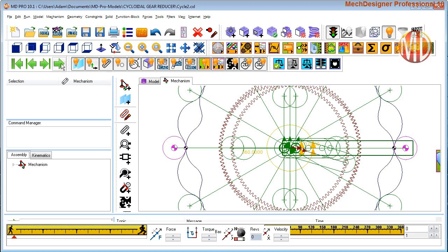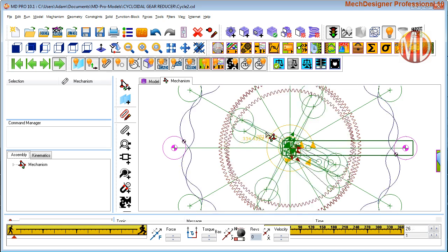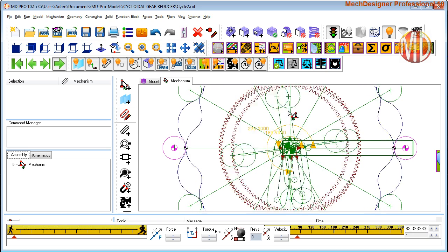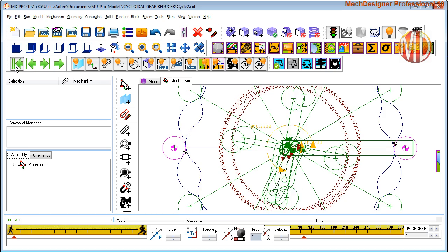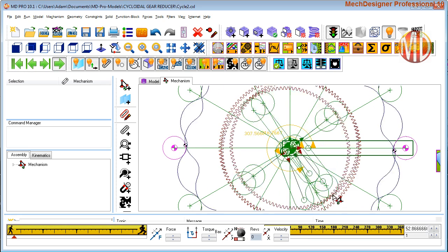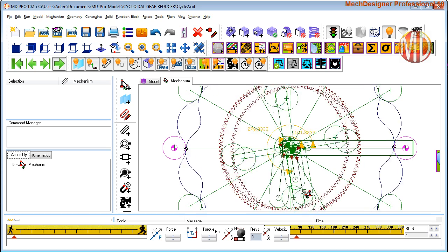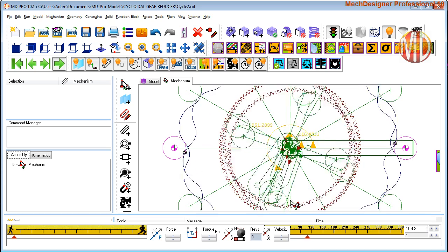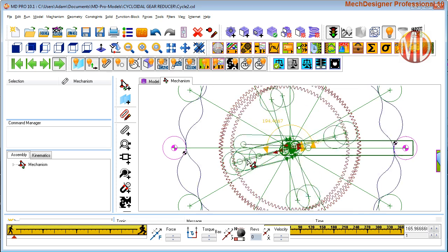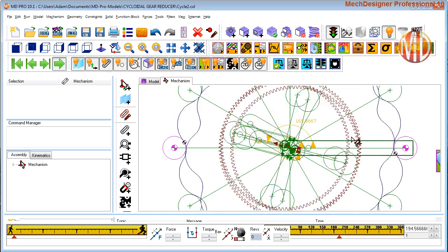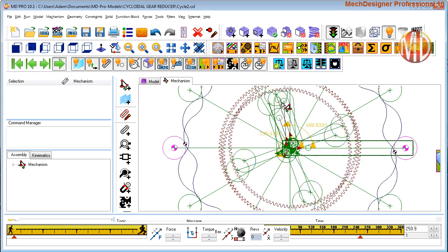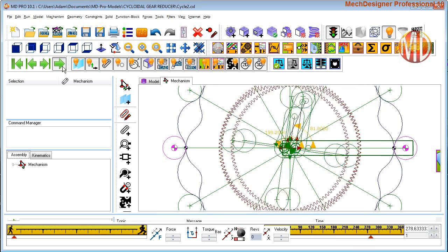And if I cycle that, you'll see that there are two sets of holes orbiting around each other, more or less. Okay, ready for the next step. What we've got to do now is add to the output shaft a number of pins so that the holes through the lobed rotors can continuously move the pins around at constant velocity.